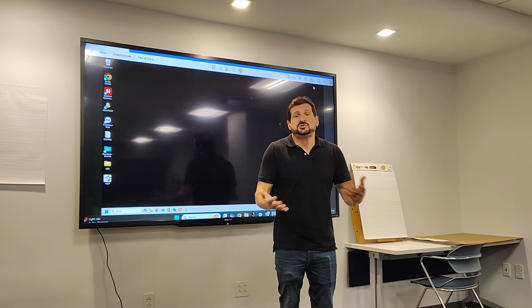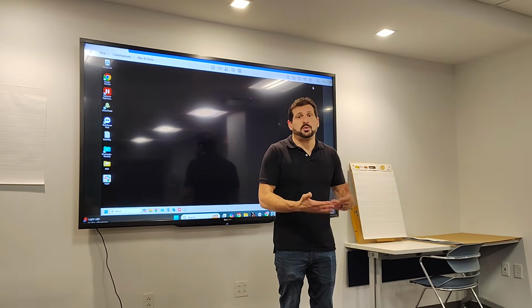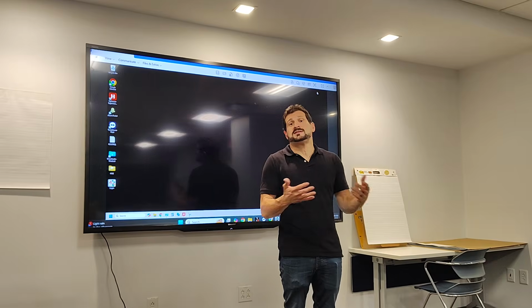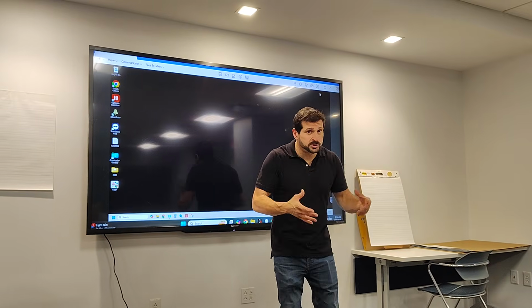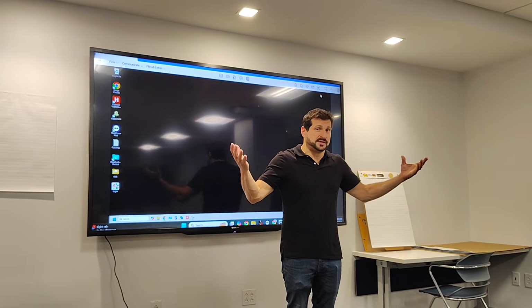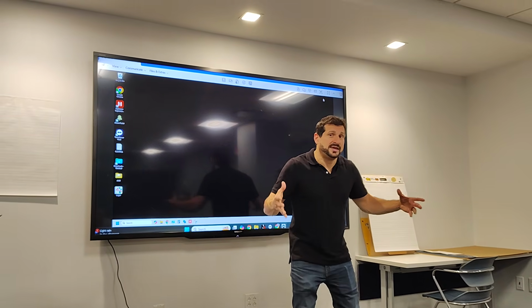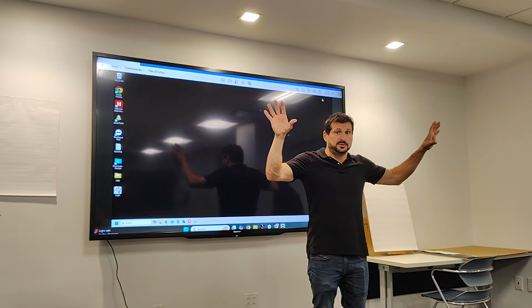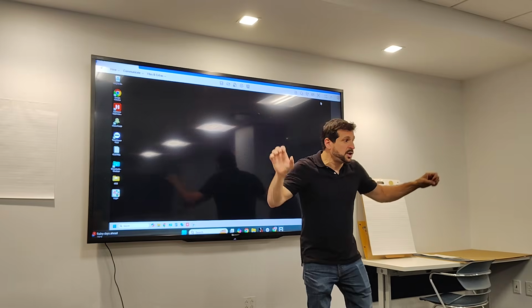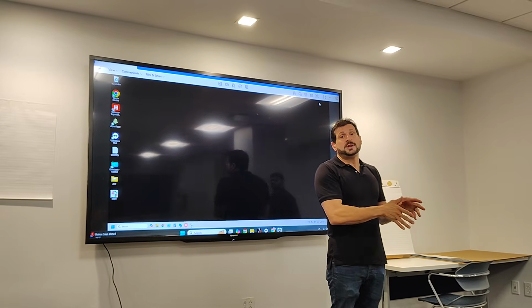I cannot attest to the quality of the programs or how they're even written. I can't attest to the sequences of them. We don't know. All we're doing is integrating with an existing system that's in your building right now. So we've taken the controllers that are available to be brought online via BACnet over IP. We put them into your BMS. You now can see them.